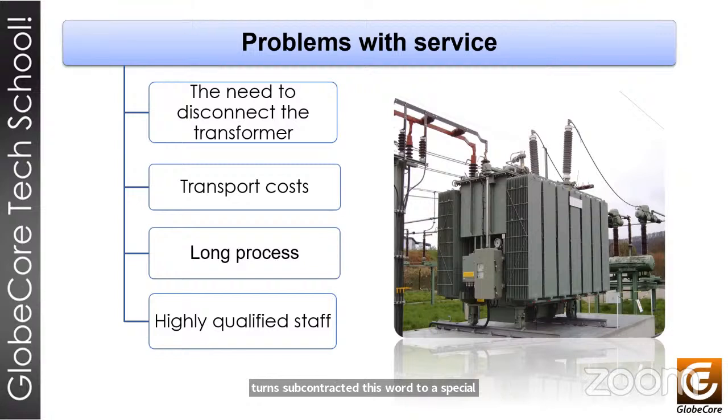During transformer dehydration, expensive equipment is rented and operated, monitoring the transformer 24 hours a day. It should be added that during the dehydration process, the power must be redirected to other transformers in the network, since the transformers must keep up. Therefore,